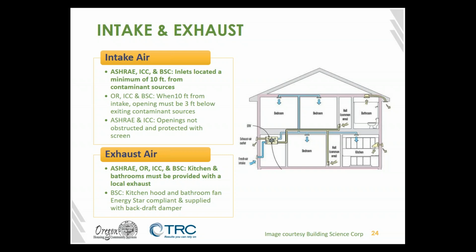It also pushes that you need to blend spot exhaust in the proper locations, kitchen and bathroom most prominent, so that you can run those beyond your 24/7 mechanical ventilation. You can spot ventilate when you're cooking. So you're pushing out any of the moisture from your cooking, any of the food particulate and contaminants there, or if you're working on gas grills, gas burners, that you're pushing out any of the combustion CO or anything else that's coming off of that, of any incomplete combustion off of that burner.